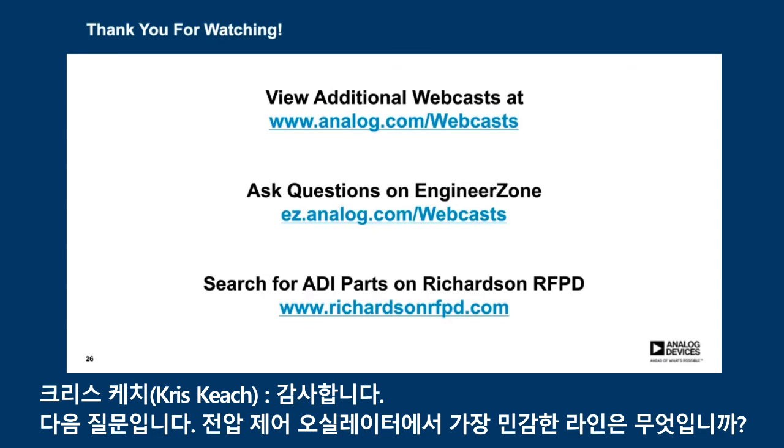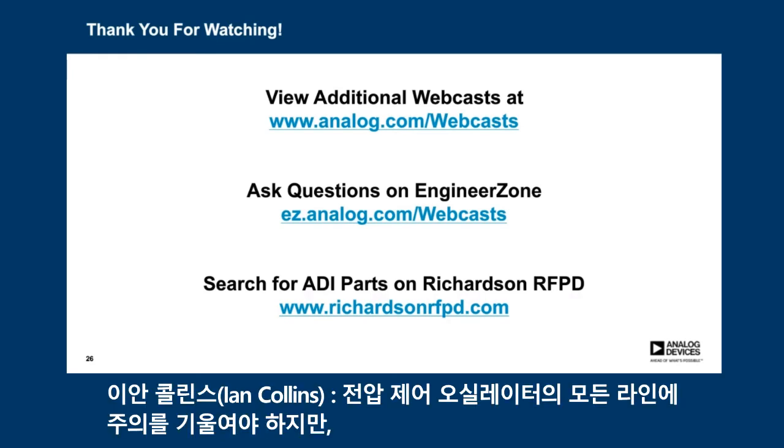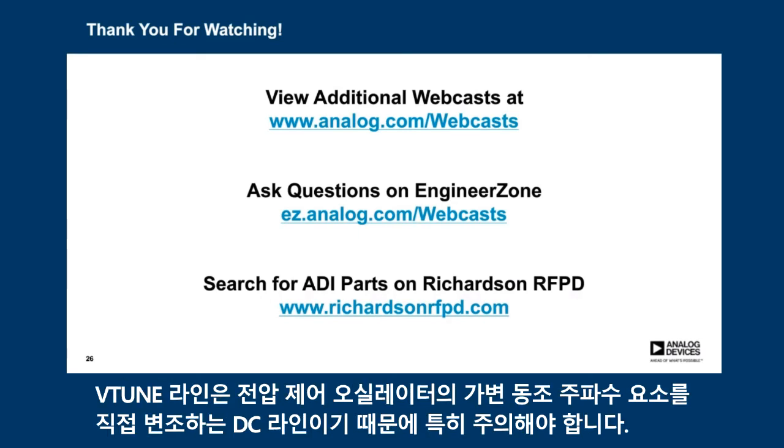Our next question for you here. On a voltage-controlled oscillator, what's the most sensitive line? Well, care should be taken with all the lines on a voltage-controlled oscillator, but the V-tune line merits particular attention because this is a DC line which directly modulates the variable tuning frequency element of a voltage-controlled oscillator.